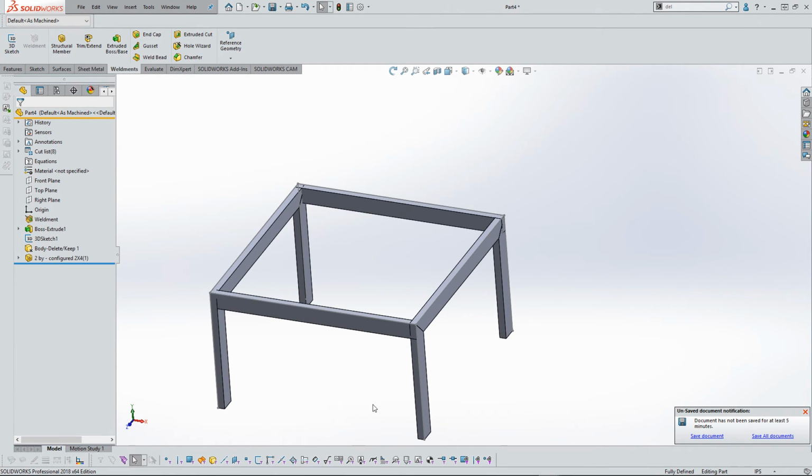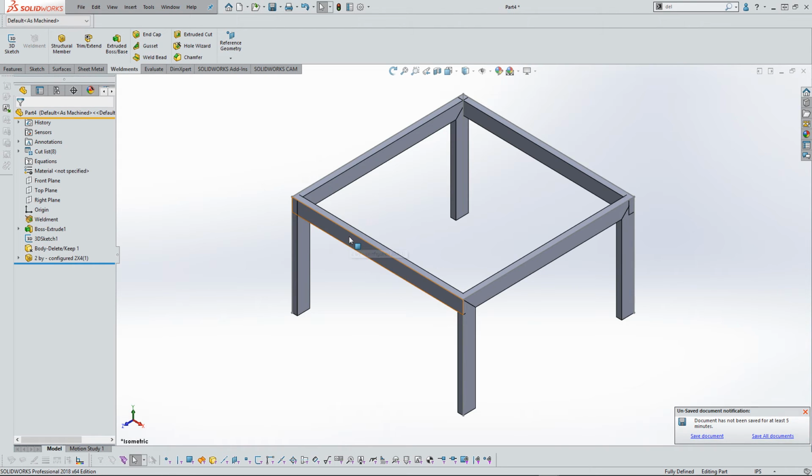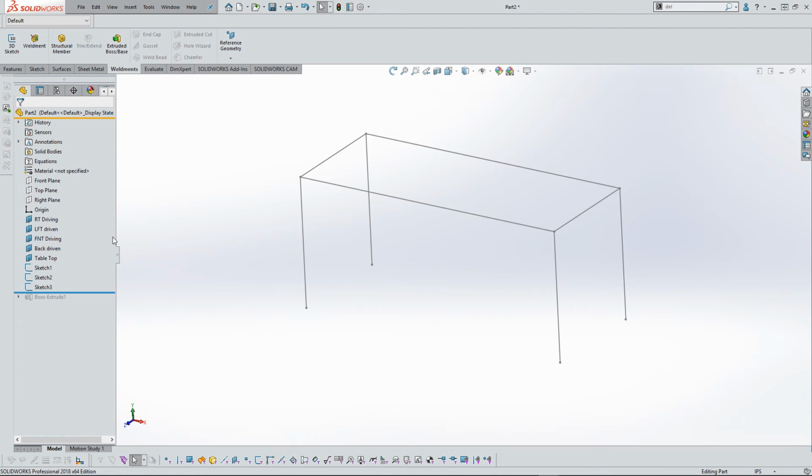All right. So now that we see this, I hope this helps you guys out with being able to see how else you can make technically 2D sketches by using the 3D sketch command, but quickly make a 3D sketch. On this, it's a pretty useful tool. I utilize it a lot. I find it being much faster than coming in and creating multiple reference planes.